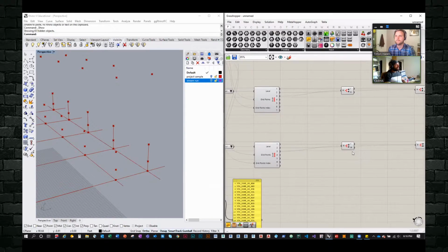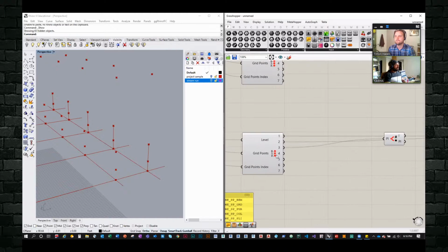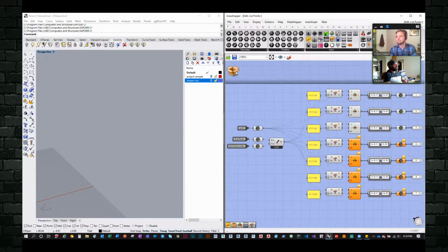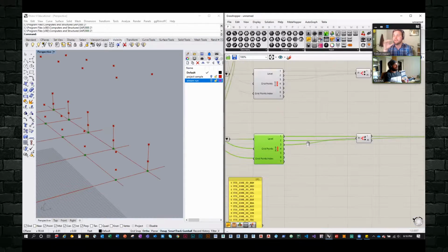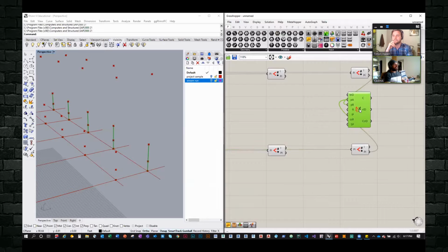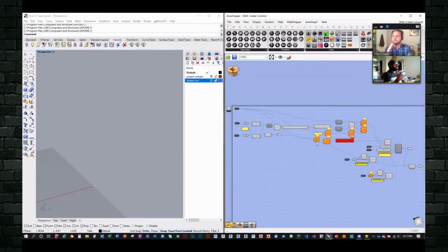Yeah, so these are clusters that I've built. Every item here, I just gave it this very fancy icon. I just created this graphic, but if you double click it, it's a bunch of native Grasshopper components that are just clustered inside of this. So then I save them as a user object so that I can create my own tab, and I can just quickly go to my own tab. It's kind of like a shopping cart.